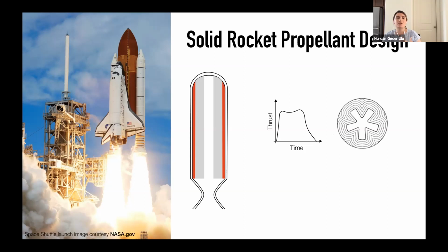But one major innovation that is aimed here is to be able to basically eliminate that red insulation region. And how that happens is that we need to be able to ensure that the last burning surface is a cylinder so that the case portions are not exposed to the flames, and we don't need the insulation.